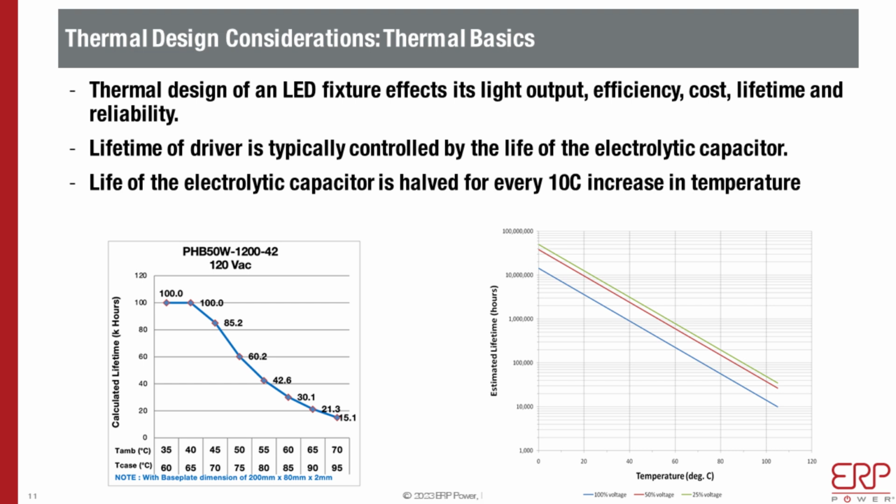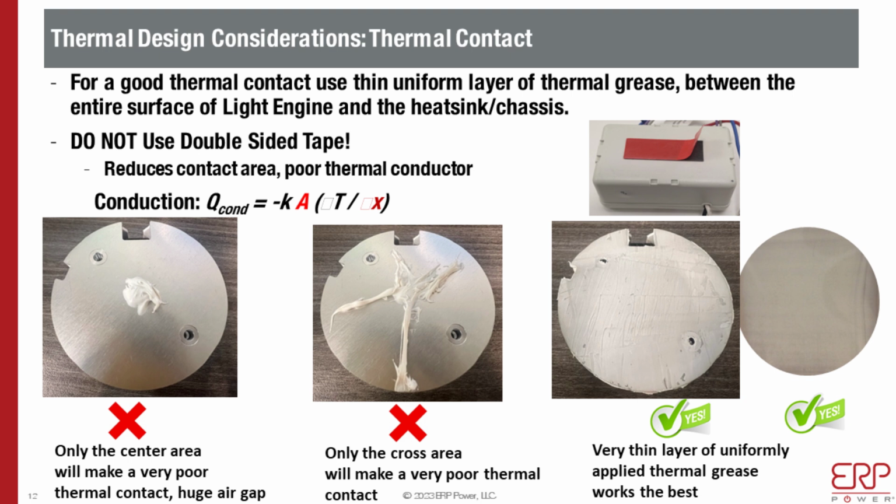The graph on the right shows the capacitor on a logarithmic scale, so the exponential decay turns into a straight line. Essentially, the concept I just mentioned is that the life is halved by increasing the temperature by 10 degrees C. So every 10 degrees C you can cool off your system, you're doubling the life. Just think of it that way.